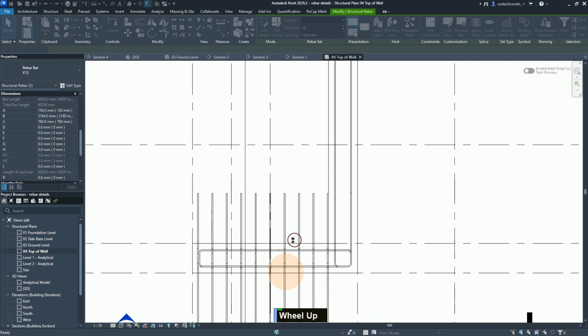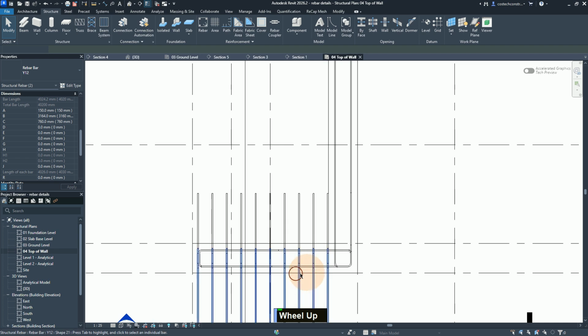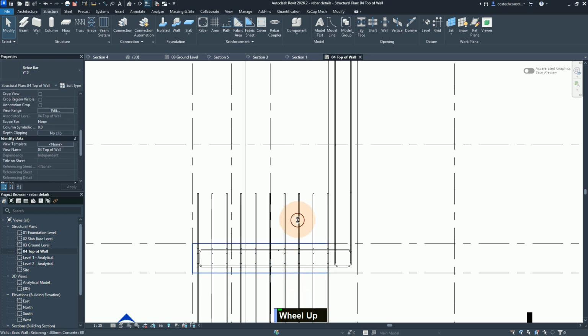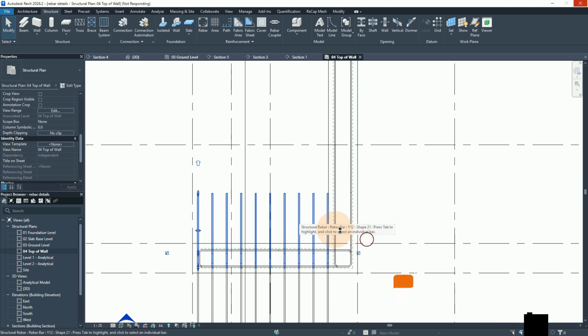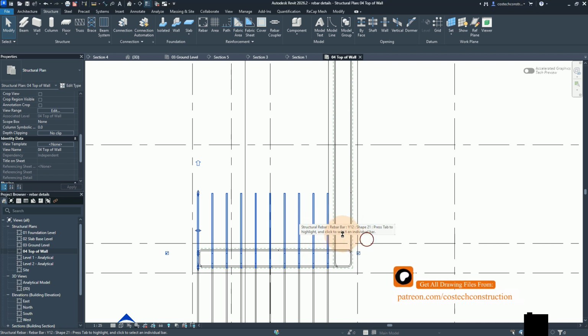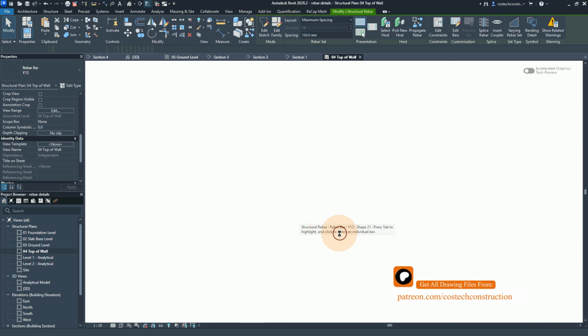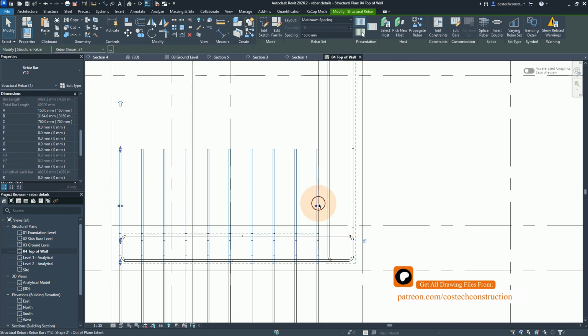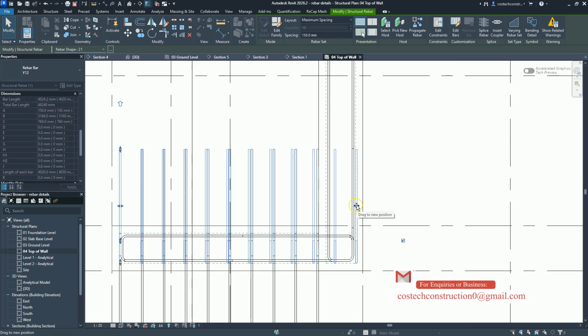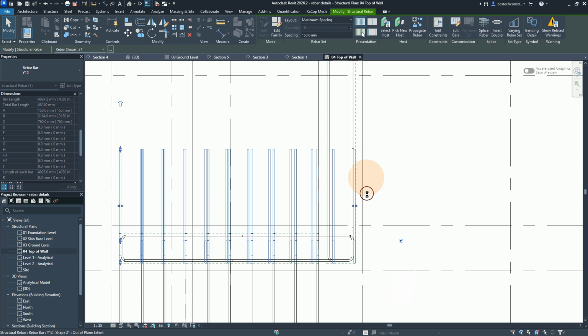This other wall edge will be for the near face. So the far face is this side. We select the rebar from this other side. And now for the far face, I will come to this side of the model. And then we can drag this one up to the rebar here, the cover at the edge for the far face edge.